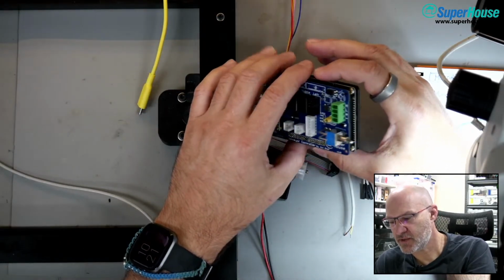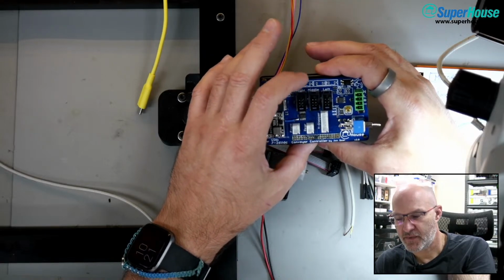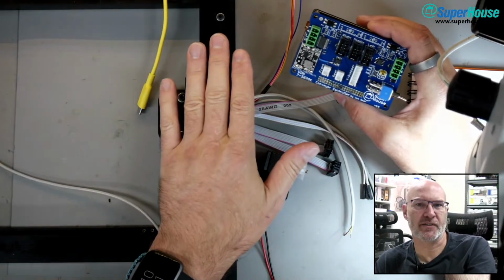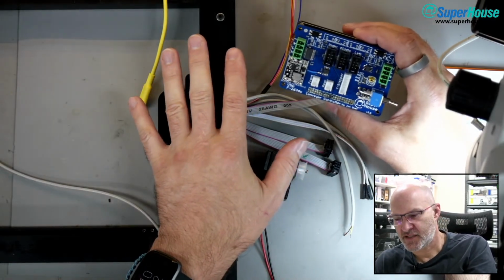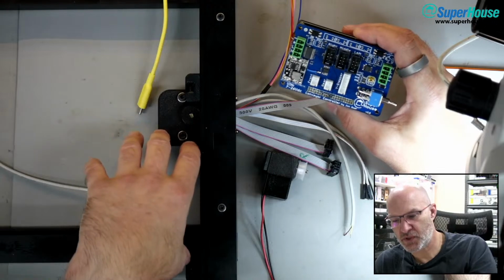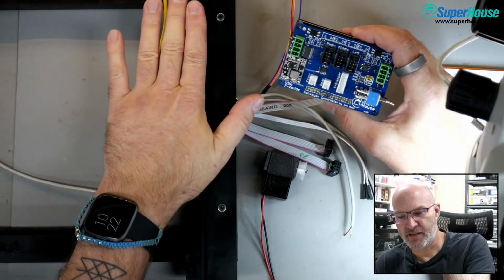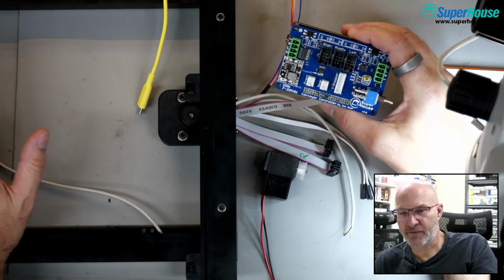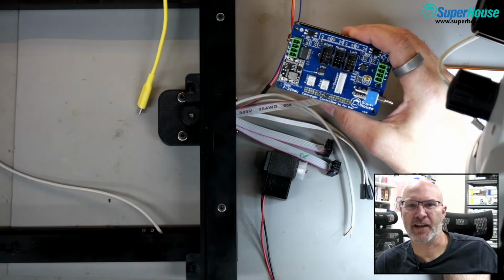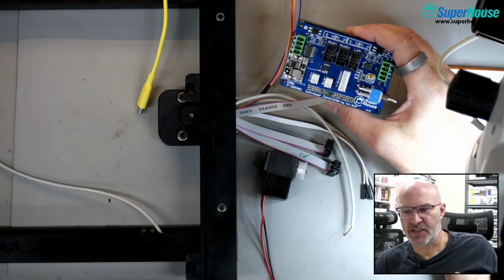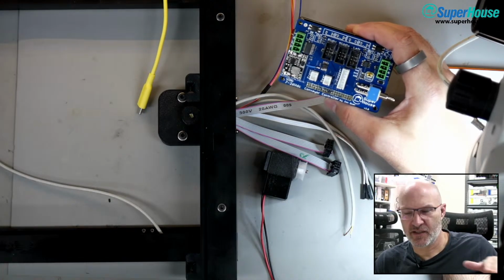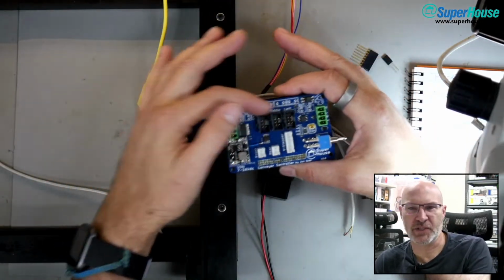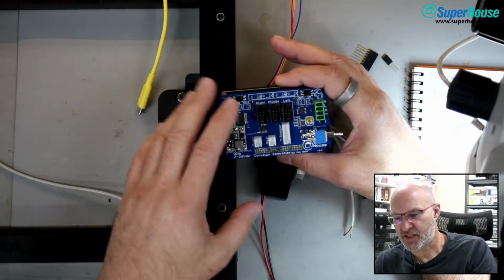But for now, my first step, I'm not even going to use that, because what I'm going to do is put one of these in front of the reflow oven and set it so that we can just queue up boards on the conveyor and then have it run on a timed basis. So the Iron 6 reflow oven does not have ready in, ready out, because it doesn't have board sensors. It just accepts whatever comes in on the conveyor. So there's no communications required for that.